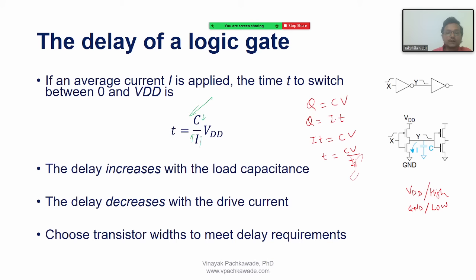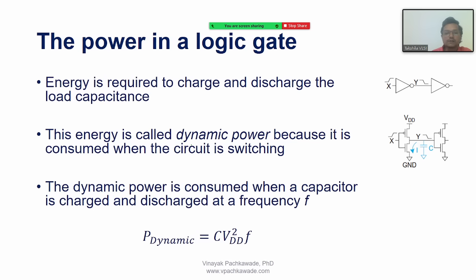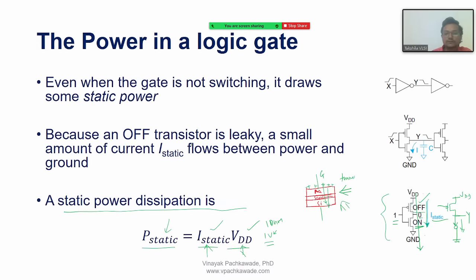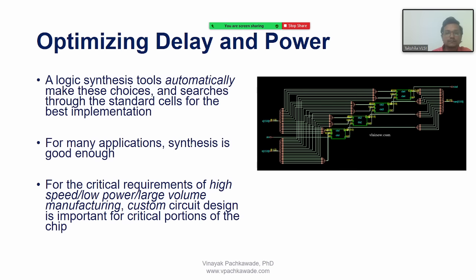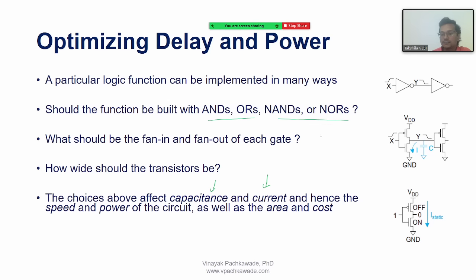And if the current transistor is wider in physical size, it is bigger, then the current will be more and the delay will also come down. So with supply voltage also smaller, the delay will come down. Understood? Yes. Okay. So like I said, we got this understanding by analyzing this simple cell.